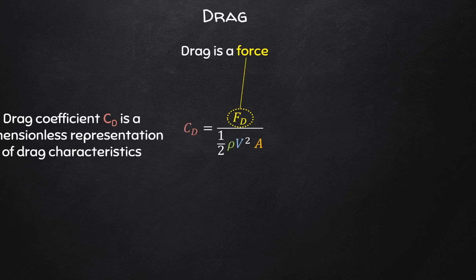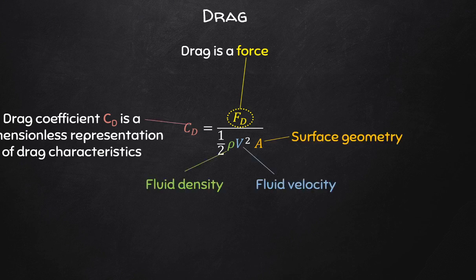Okay, now as we have defined the drag coefficient before with the following equation, which is just another version of the Darcy-Weisbach equation. We've been using the Darcy-Weisbach equation in piping system design. We can also have a similar equation for the case of flat plates. So here where we have CD, we've been using the friction factor, which is F prime, for piping system design.